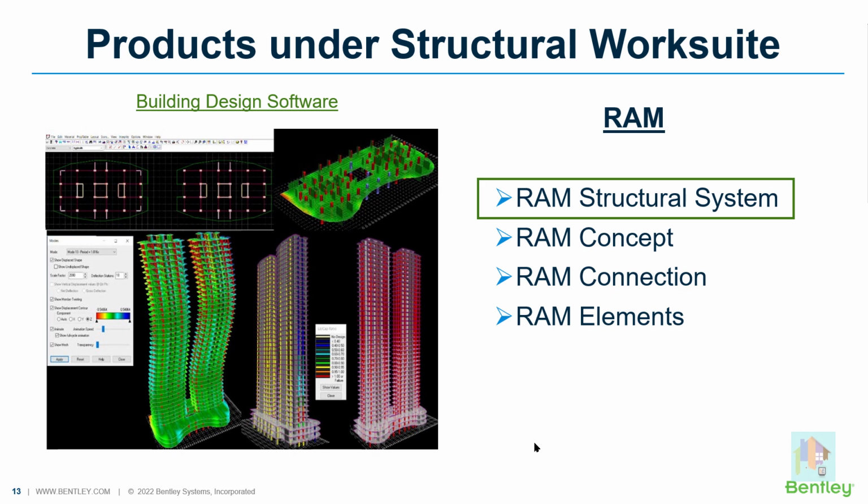If you ask me what is the best software that we have under the Bentley portfolio for building structures, RAM Structural System is our best product for any tall or medium to tall structure design. I'll show you some examples where we can use RAM Structural System. It has great capabilities like construction stage analysis and drift control. There are multiple diaphragm options like the pseudo diaphragm or the flexible diaphragm. All those systems like the outrigger truss or the belt truss, which are required for tall structure design, are already equipped in RAM Structural System.